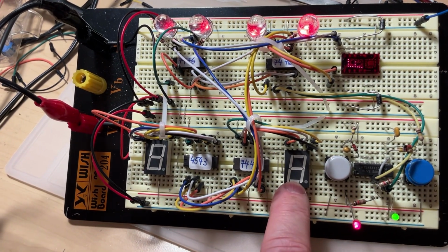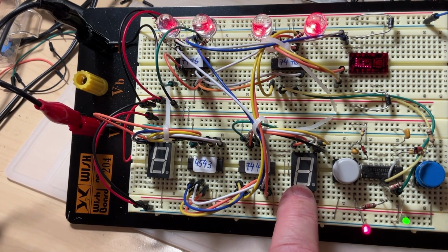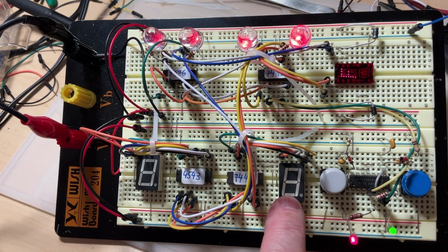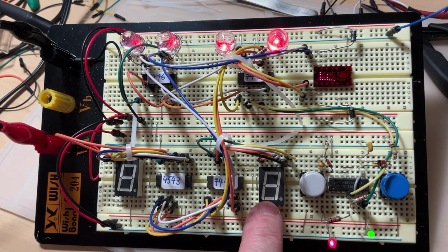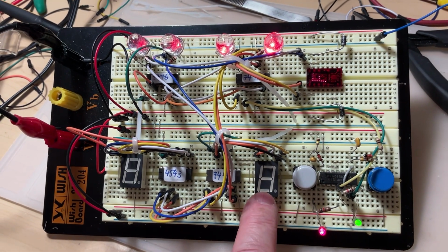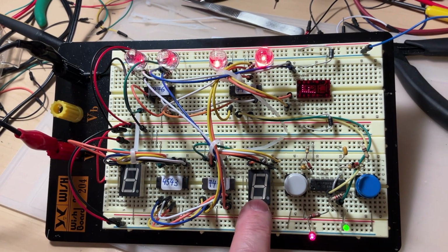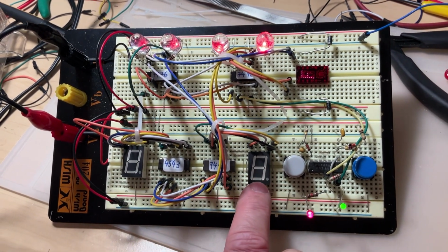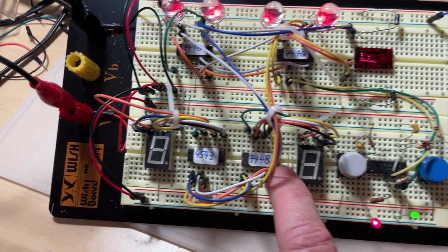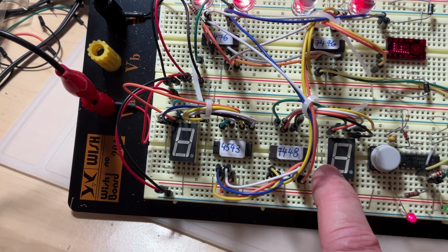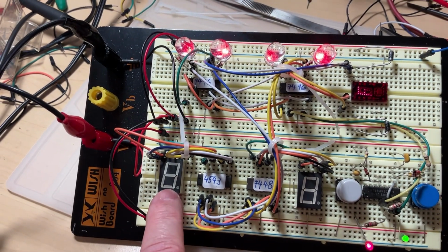because of different reasons. One reason is the display may simply not be energized. If it is not energized, whatever you do, it doesn't show anything. The second reason it may be blank is because of this. The display may show you the number 15 blank if the decoder is 7447 or 7448. The third reason is this one here.